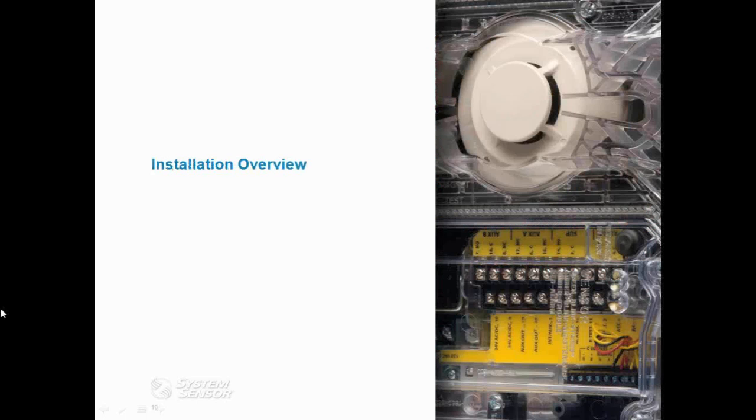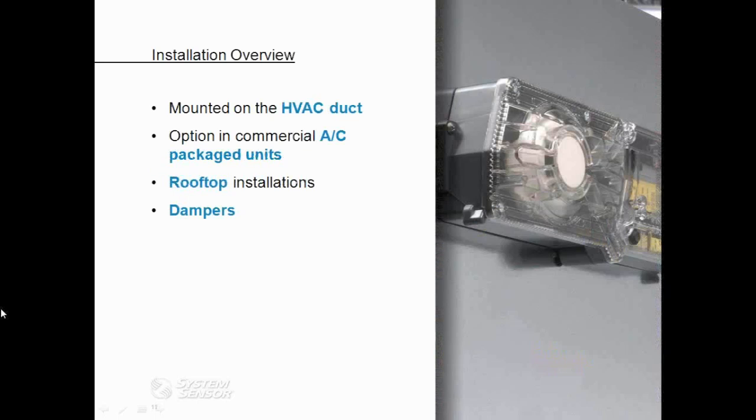Okay, thank you. The next section of the presentation will provide an overview of the installation of duct smoke detectors, and will highlight various applications that they can be utilized in. Duct smoke detectors can be installed in a variety of different applications, including mounting it to the ductwork itself, installed in a commercial packaged unit or rooftop unit, outdoor rooftop applications, and then installation on smoke or fire dampers.